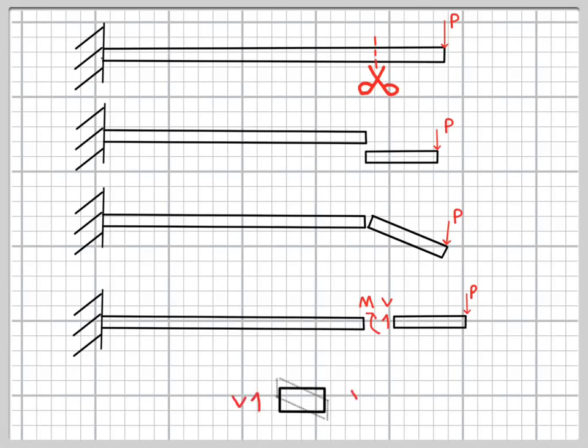With shear force, we say if the shear force is tending to rotate the small chunk of beam that we've imagined cutting off in the clockwise direction, then it's positive. And we say a bending moment which tends to curl the beam so that it's sagging, as in the diagram there, is positive. These are the normal sign conventions for analysing beams.